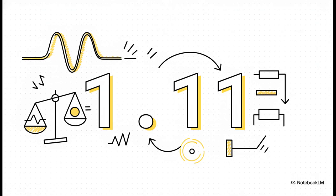And that mathematical journey gives us the form factor, which for a sinusoidal wave is exactly 1.11. This number is just a simple constant born from dividing the RMS value by the average of a half cycle. You absolutely do not need to stress over deriving it every single time. It exists just to act as a bridge. It's a mathematical tool that helps us step from the reality of an undulating, changing wave into a functional, steady value that we can actually use in real-world engineering.